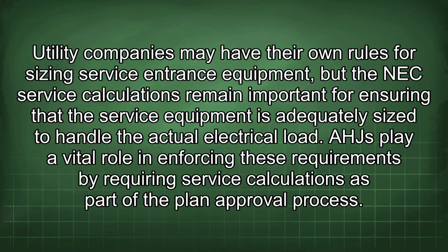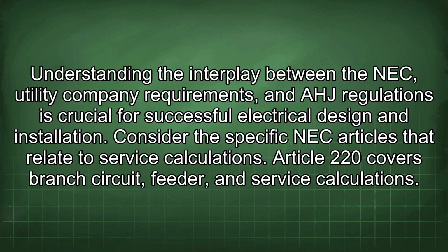AHJs play a vital role in enforcing these requirements by requiring service calculations as part of the plan approval process. Understanding the interplay between the NEC, utility company requirements, and AHJ regulations is crucial for successful electrical design and installation.